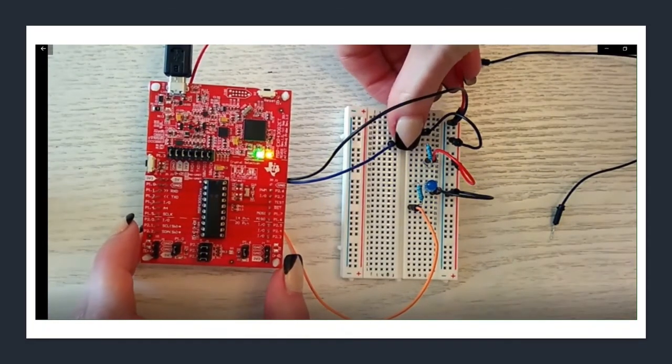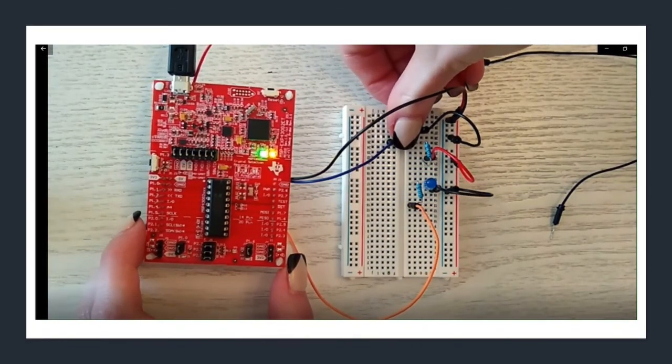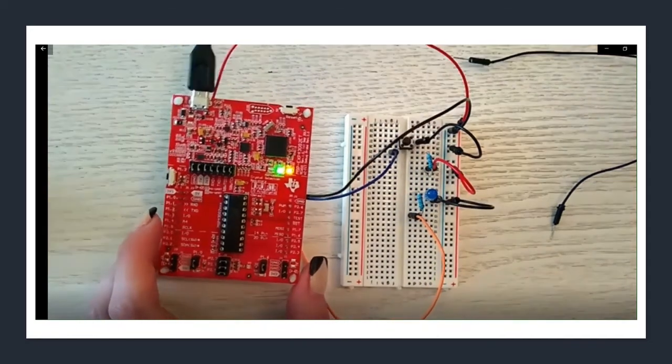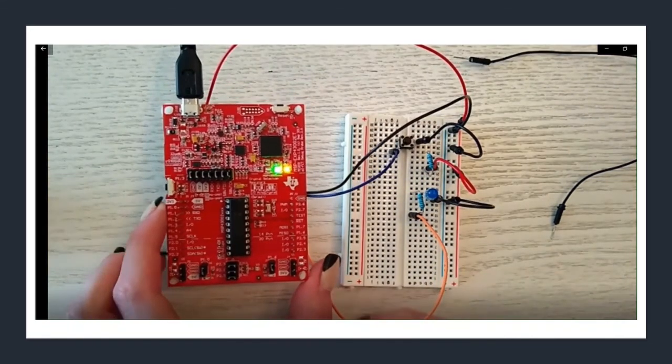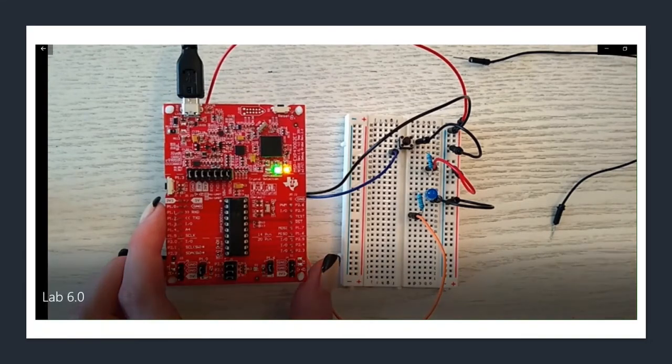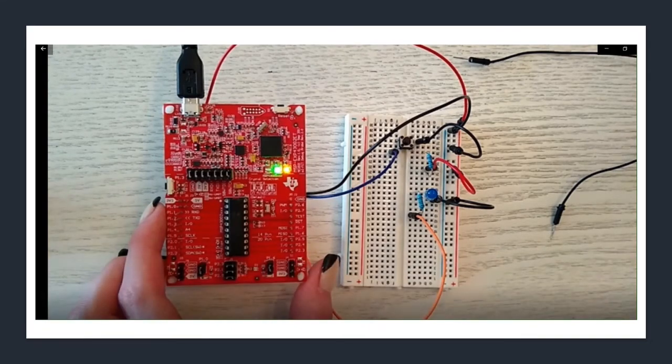So what would happen if the board LED was lighting up but not your external LED? That would mean you probably wired something wrong on your breadboard. That's why it's good to use the same pin numbers. Another word of caution: when you're connecting your LEDs, don't forget to put in those resistors. Add those in between the LED and either the power or the ground. I know I've already mentioned this, but if you don't, you will ruin your components.